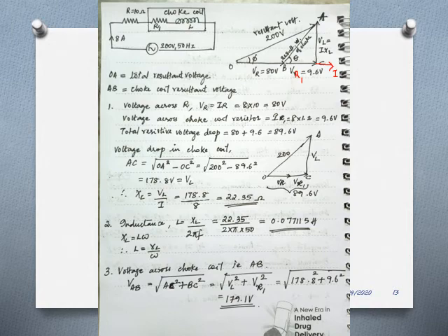For the time being, I have just marked an angle theta. Even if you don't mark it, it is also fine, but you have to definitely mark the phase angle phi. So thus we have drawn the phasor diagram of the choke coil alone, which is BC, AC and the resultant AB. Now from this resultant AB, we are going to construct the resultant of the total circuit.